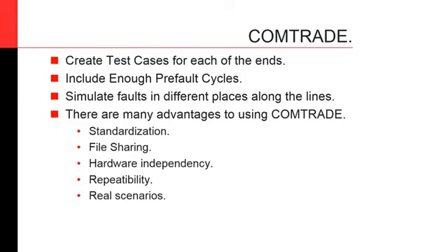You can play it back in the relay and see if it operated properly, and if it didn't, why that happened. Also, most, if not all, simulation tools used today to simulate power systems have the ability to generate ComTrade files, which is what makes it so attractive.